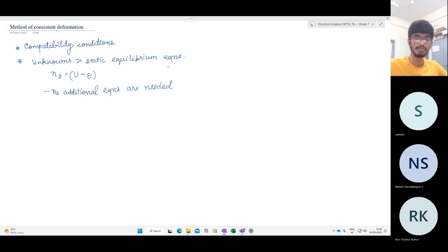So how do we solve the problem given a truss? Right. So today we are going to look at trusses. It's a simple truss. So this is a statically indeterminate truss. Right? How many reactions do we have? We have 4 reactions. And how many global equations of equilibrium we have? 3. So its external static indeterminacy is equal to 1.